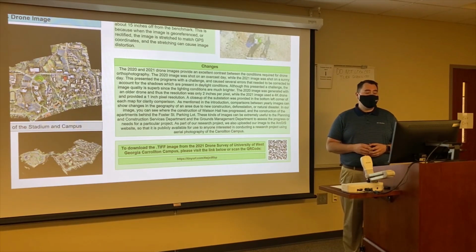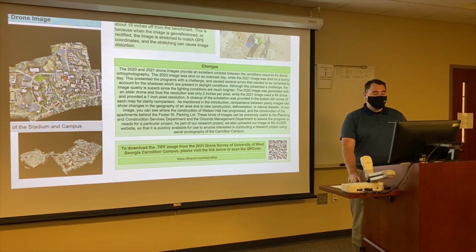This presented the programs with a challenge and caused several errors that needed to be corrected to account for the shadows present during daylight conditions. Although this presented a challenge, the image quality is superb since the lighting conditions are much brighter. The 2020 image was generated with an older drone, and thus the resolution was only 2 inches per pixel, while the 2021 image used a 4K drone and provided a 1-inch pixel resolution.